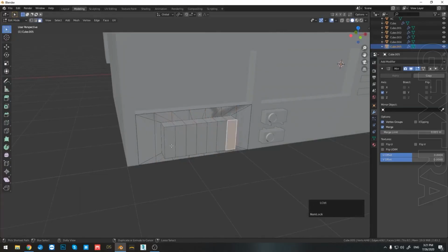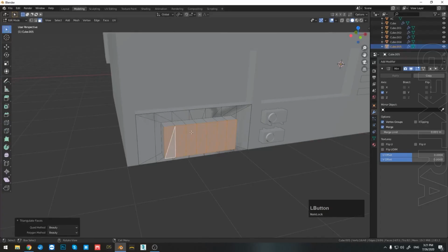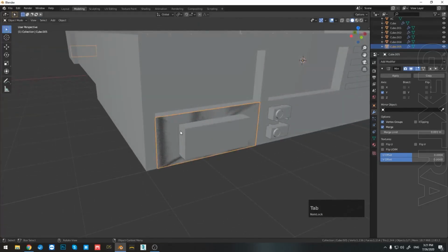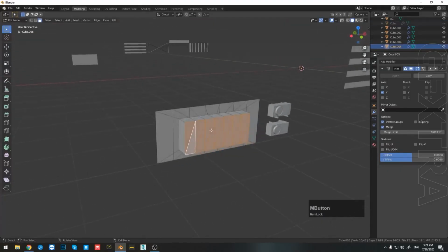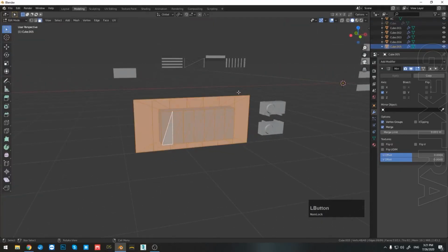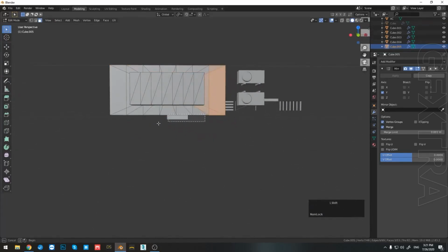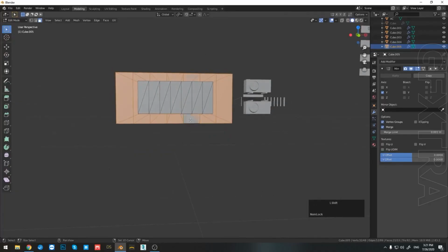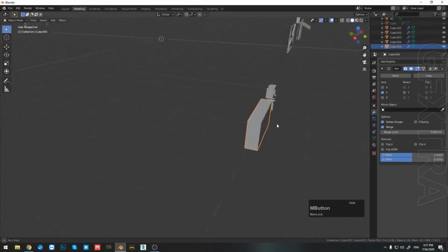Now select these faces right here, then right-click and select Triangulate where you're in face selection, and then press Tab again to go back. Now hide that mesh, press Tab again here, select everything on the sides that we've made. So let's select all of the sides, like this. Then press Delete, select faces, so we have something that looks like this.